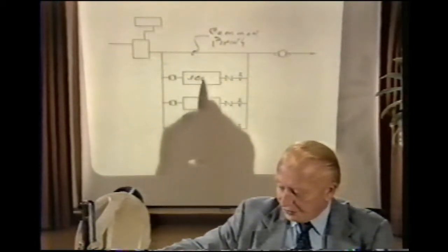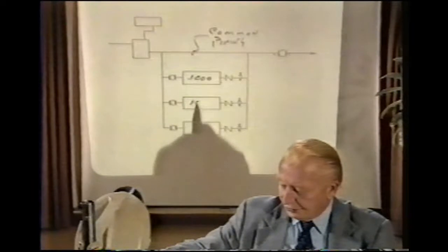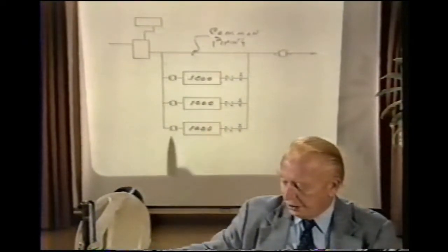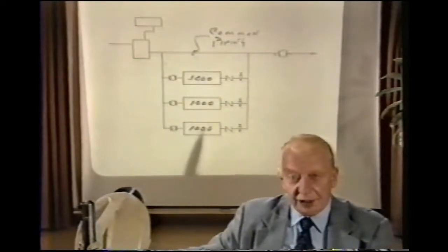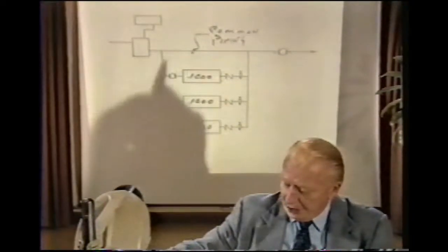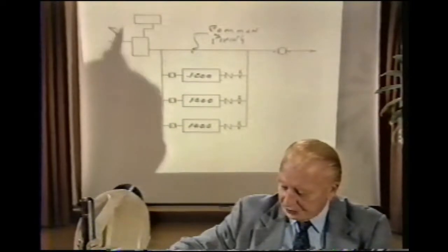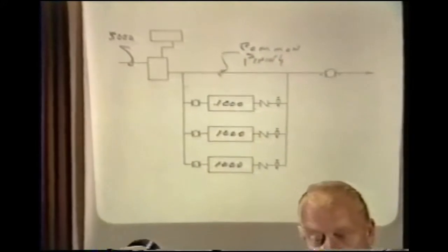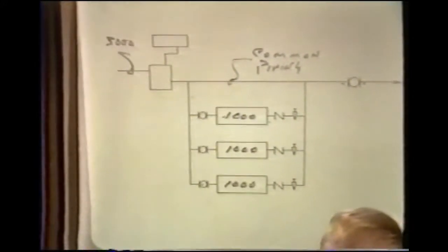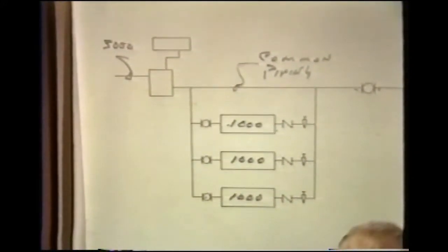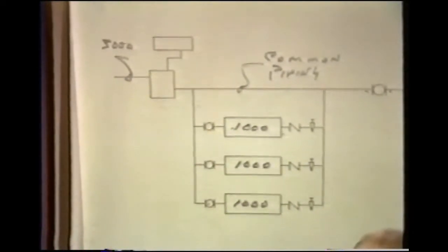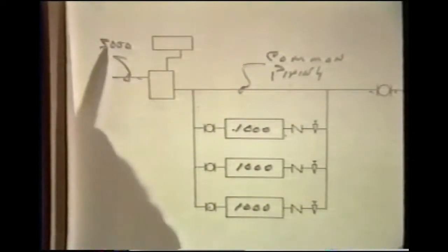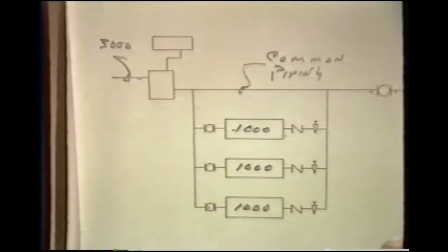Let's say each of these chillers flows at a rate of 1,000 GPM when its chiller pump is on. And we have for this system then at full load 3,000 GPM flowing through the piping system. As the two-way valves in the system modulate and change flow, the flow change is stated by a flow change in the distribution system.